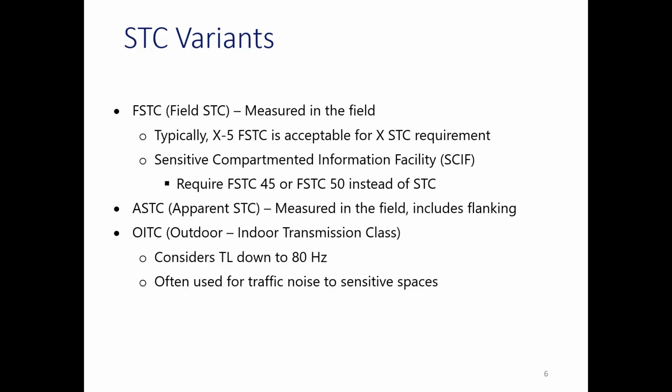The sound goes up, it excites the roof structure, that lightweight metal roof. It's like the old movies where train noise is heading down the train track and the robber puts his ear up against it. The sound just traveled easily through that lightweight roof, and then the roof on the other side basically became a speaker that radiated out all that sound. So that flanked. Like the military term, you're coming in around the side. It flanked the main partition. So you might have that through the ceiling, through the floor, any kind of other partition like that.